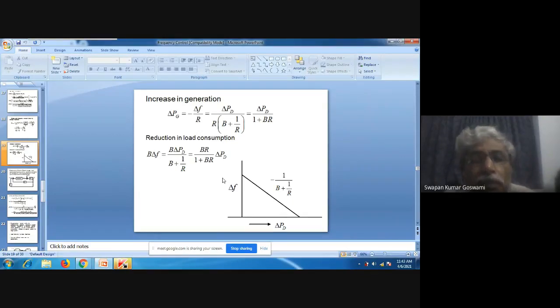That means frequency control is not there; in the true sense, frequency control is not there. If you depend upon the free governor action alone, then you cannot regulate your system frequency. You cannot control your system frequency with the variation in demand. System frequency will be varying. It is bound to vary because governor alone cannot bring the frequency back to normal value.